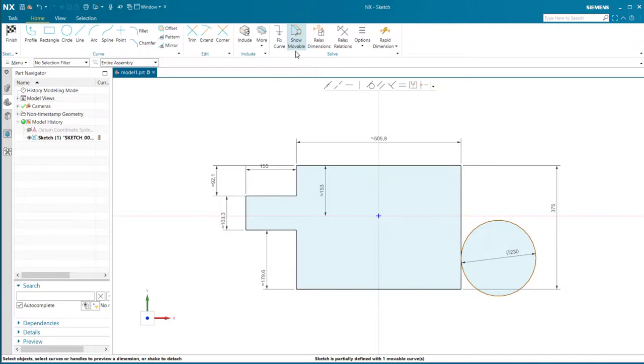So in summary, we've learned to enable and disable the new sketch. We've explored the Create Sketch dialog, where we've come to this point by creating a sketch. We've looked at the new Solve group, and we've also created a sketch and some dimensions and seen the differences with the scene bar and the relationships between some of the sketches within the sketch itself.